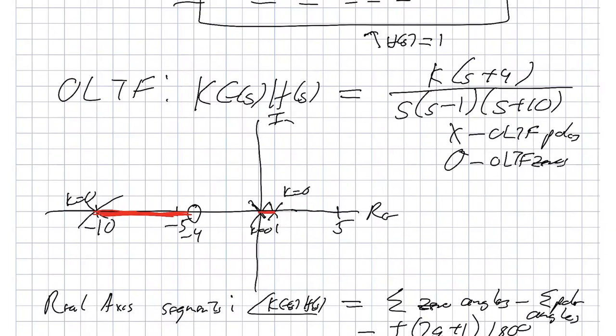Let's do green here: 1, 2, this location here is sigma 0, which is -2.5. Notice it doesn't happen to be on the locus; it's on the real axis, but not on the root locus. It may or may not be, that doesn't matter. So we know these lines are going to cross at -2.5.